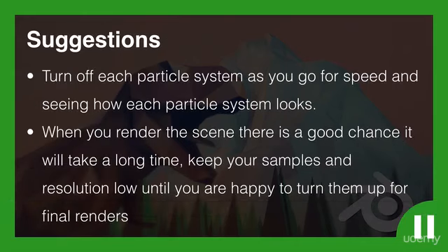So to give you some more suggestions, turn off each particle system as you go for speed and seeing how each individual particle system looks. And then finally, when you render the scene, there is a good chance that it will take a long time. So keep those samples and resolution low until you're happy to turn them up for final renders.